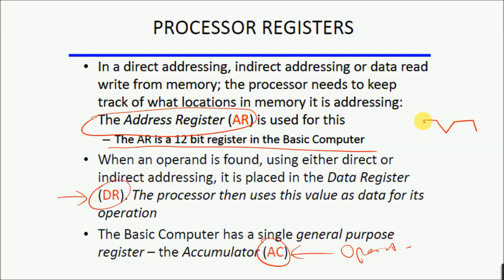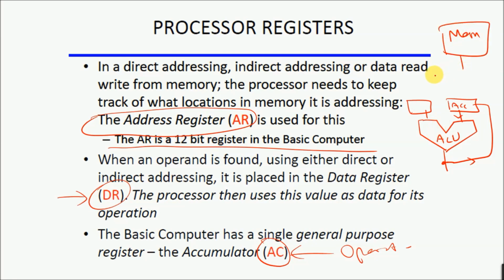Let me tell you here. So this is your ALU, this is the accumulator, and this is your second operand. Now your second operand is being fetched from the memory, and when it is fetched from the memory, it is placed on the bus. But bus is not a storage. So whenever the next micro operation is executed, the data for the next micro operation has to travel from the bus, the data or address. So bus is continuously being used, it is not storing the data.